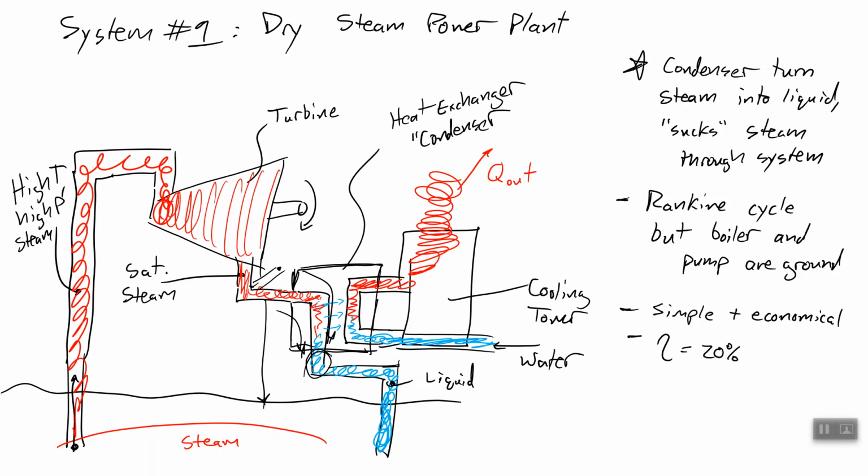The pressure won't be as high as you'll run in a standard coal-fired power plant or a combined cycle power plant. So you can't extract as much work because there's not as much potential there. Okay, and then regarding how much steam, a 55 megawatt plant will require about 100 kilograms per second of steam. And that's quite a bit.